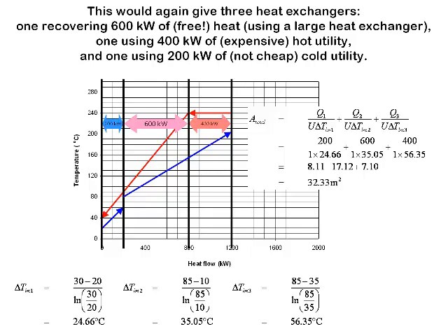Similarly, on our cold utility, if you remember, initially we would have required 800 kilowatts of cooling water heat transfer. We've reduced that all the way down to just a quarter, just 200 kilowatts. Cold utility isn't as expensive as steam, but even so, it costs us money, and we've reduced that cost to a quarter. So that's a substantial saving.